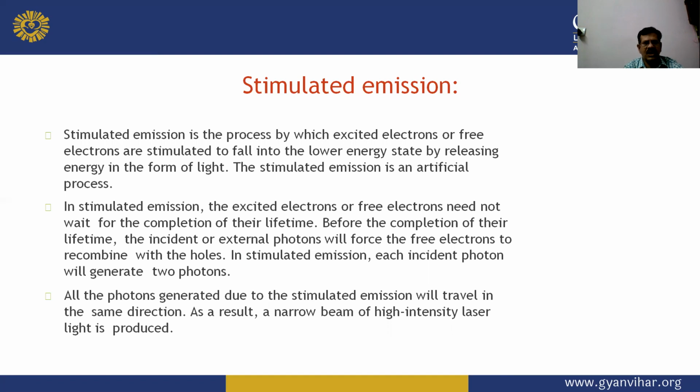In stimulated emission, the excited electrons need not wait for completion of their lifetime. Before the completion of their lifetime, the incident or external photons will force the free electrons to recombine with the holes. In stimulated emission, each incident photon will generate two photons.